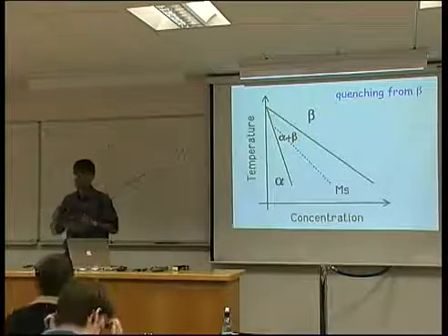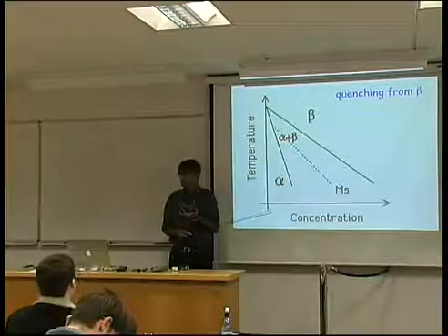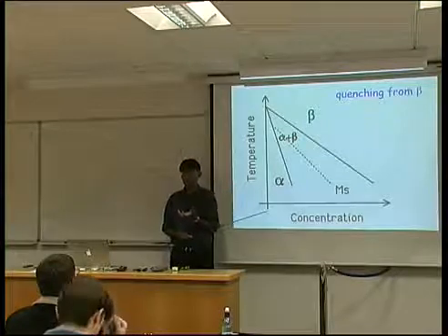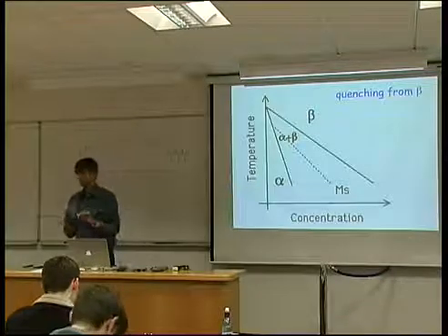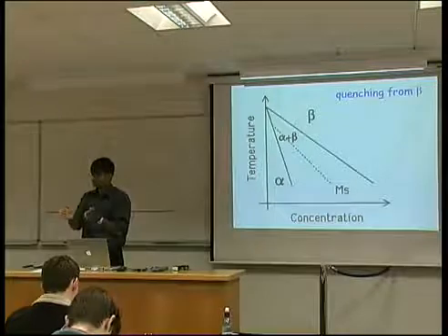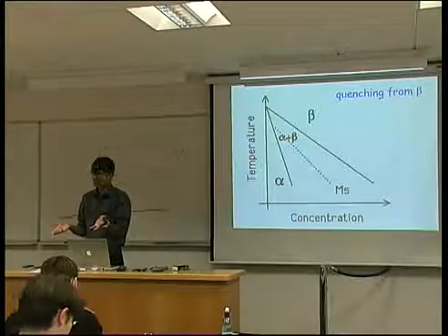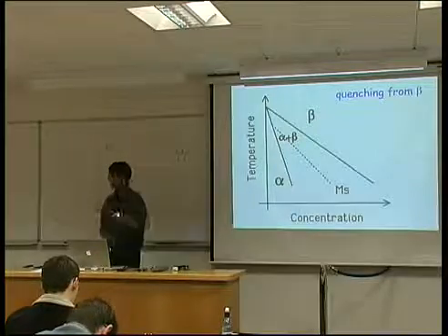It's a non-equilibrium phase. First of all, we are not allowing elements to partition. So you're trapping elements which really don't want to be there. Secondly, Martensitic transformation is associated with a lot of strain, because you're deforming the pattern in which the atoms are arranged, and therefore the overall shape of your crystal must change, and that shape has to be accommodated with the surroundings. So you have a lot of strain energy.